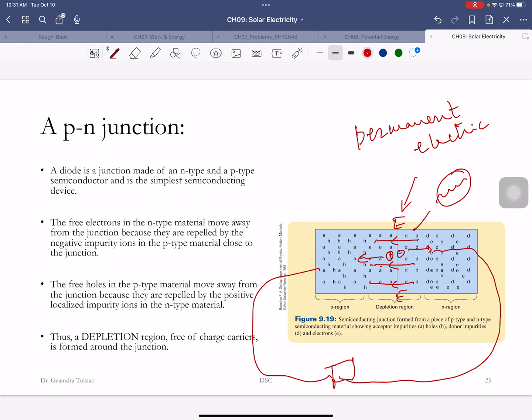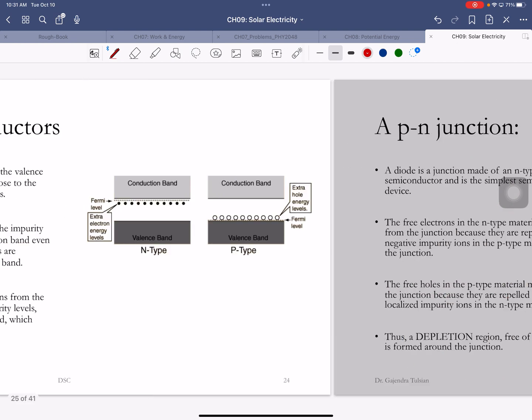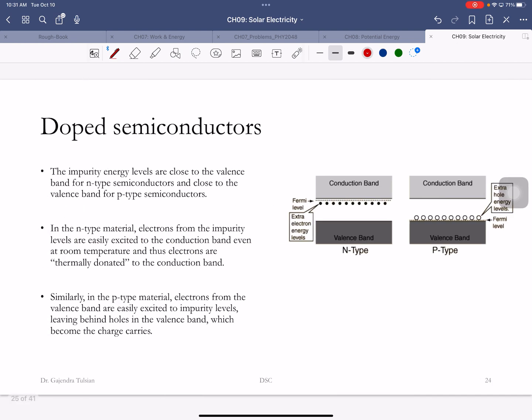I guess, N-type impurities have one electron? I'm sorry? You said N-type impurities have one electron? One electron extra. They have 5 valence electrons. Yeah. Okay. And the crucial part is you've got to choose the right impurities whose level is sitting right below this conduction band, so these electrons can be thermally excited. It's very cool if you guys understand it.